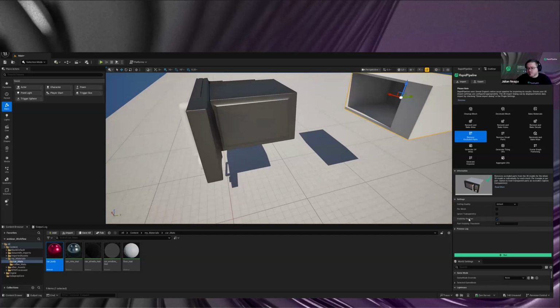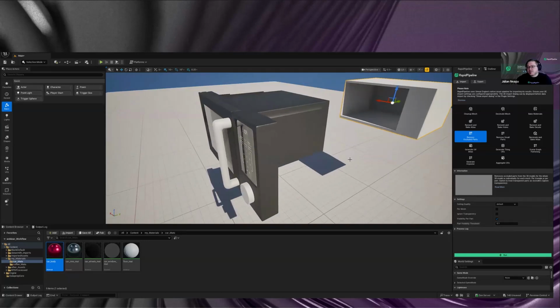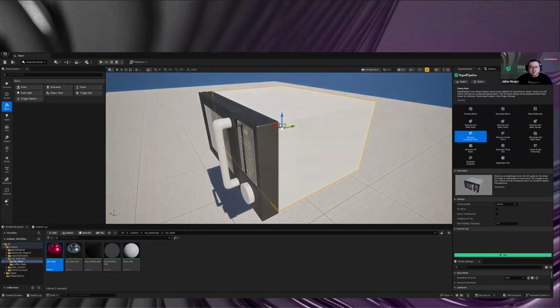So actually first it does a pass on the triangle side and shoots rays from all the triangles, right? It's a pretty cool algorithm. And then checks, hey, am I visible or not? And then it actually has a threshold here, which you can also change, which are right now in the defaults, they're perfectly set in terms of working with most assets in a good way. And then it actually increases the selection to the actual mesh lump level, which I guess in Maya would be called shape. So it's not a mesh level, but it's the smallest coherent part of connected triangles. And it actually looks on the mesh lump level and then deletes those mesh lumps automatically. And as you could see, the pizza was not touched. Pizza is still there, everything good.